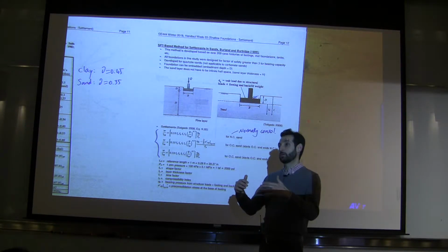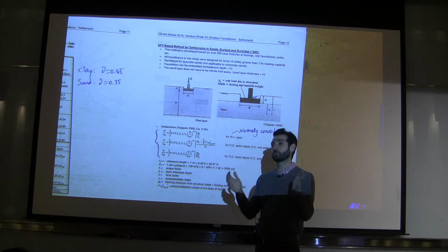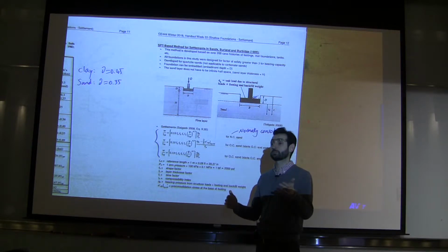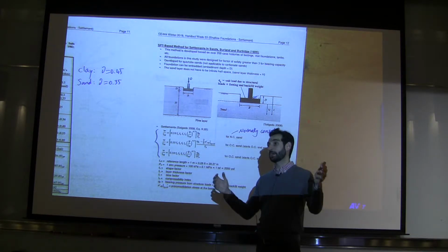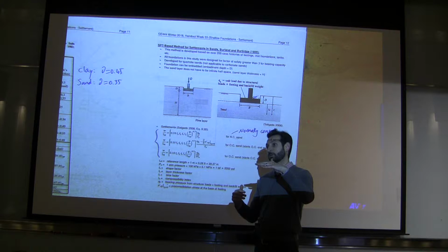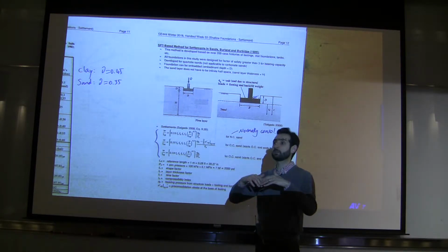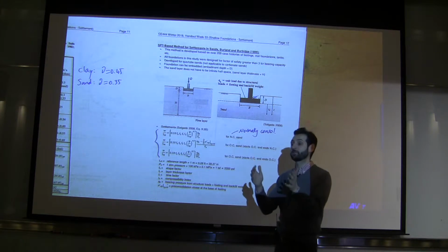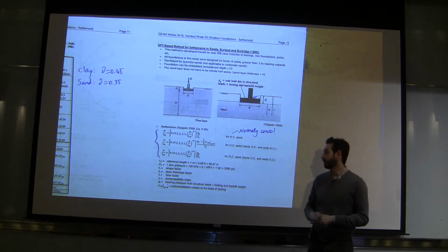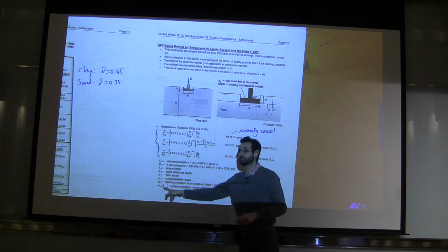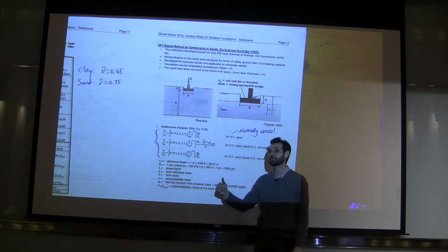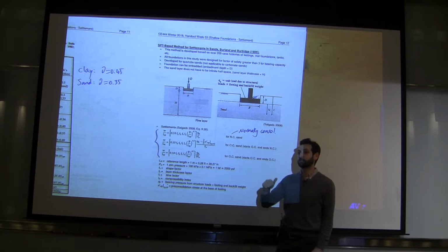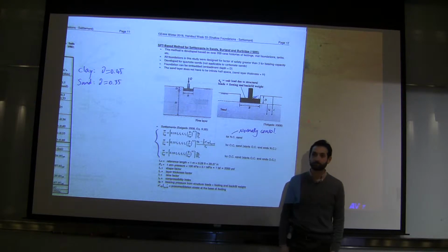So let's say before you start building the foundation, your stress was 10, and then you excavate it, so your stress goes to 0, and then you add 60 load on, so now it goes to 60. And that 60 depends whether you're backfilling or not. Your sigma prime Vp is the pre-consolidation stress, so it means the 10 that was there before you started excavating. Gotcha.